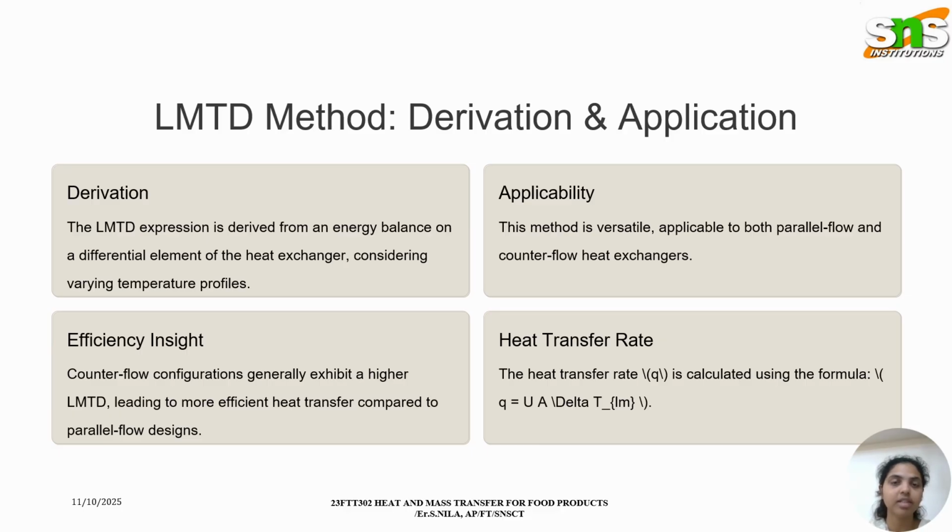This method is versatile, applicable to both parallel flow and counterflow heat exchangers. Counterflow configurations generally exhibit a higher LMTD, leading to more efficient heat transfer compared to parallel flow designs.